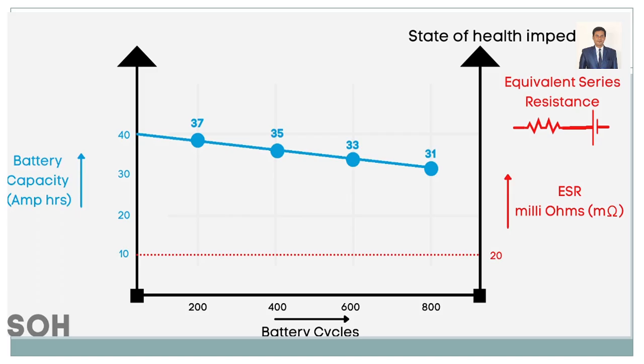Initially when you bought for the first time, it is here. Let us take the example of this only. It is 20 milliohm, right? So after 5 or 6 years, what will happen? The ESR in milliohm will increase from 40 to 60. There is a drastic change. There is a 40 milliohm difference. So what will happen during that time if resistance increases in the internal battery? The current will also gradually decrease. Correct. So that's why you can see there is a decrease in the Ah.